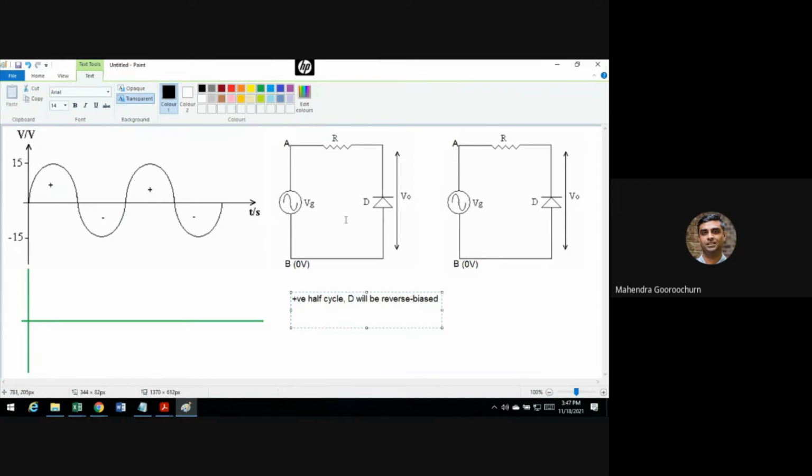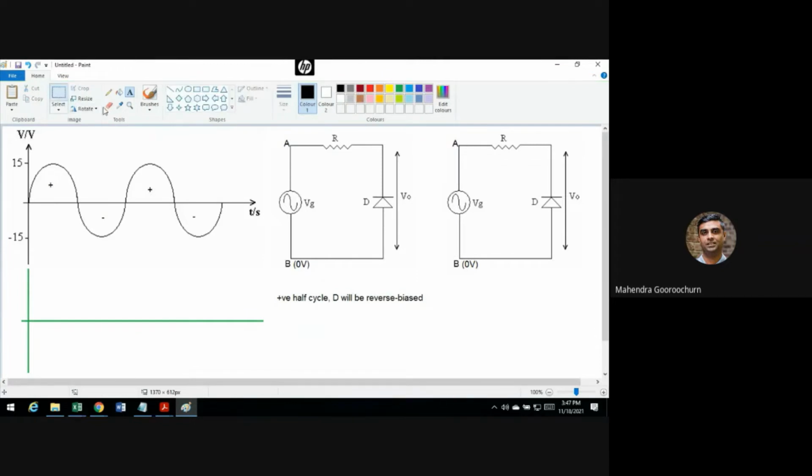So if you try to flow a current in the opposite direction to the bar, the diode is definitely reverse biased. And what you would do now, if it is reverse biased, is simply replace this by an open circuit. Reverse bias means no current is flowing. This is the situation. The question for you now: if your diode is reverse biased, what V0 would you measure here? Think well about it. What V0 do you think we're going to measure if that is an open circuit there?